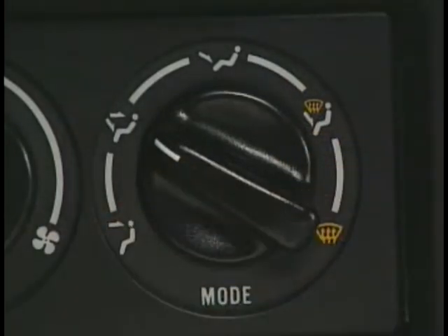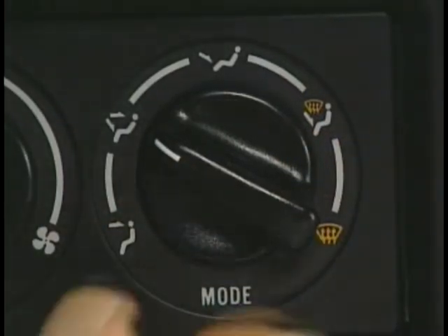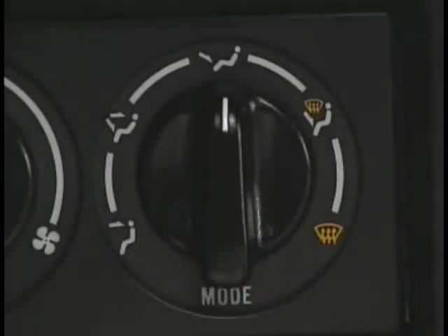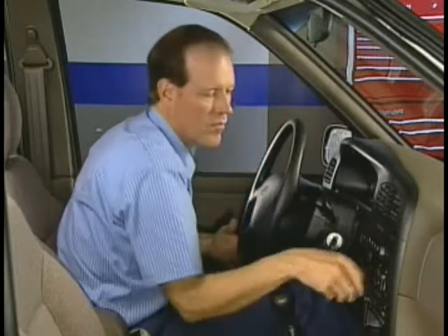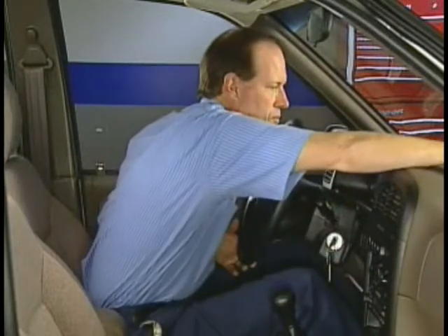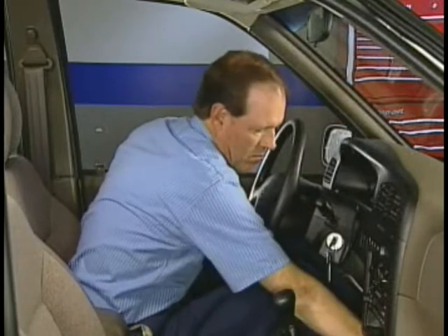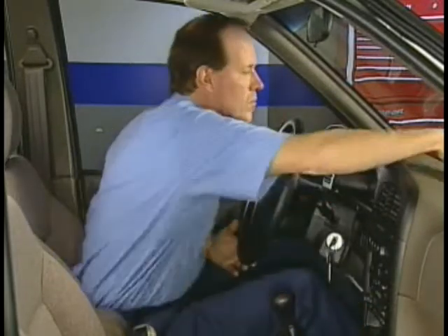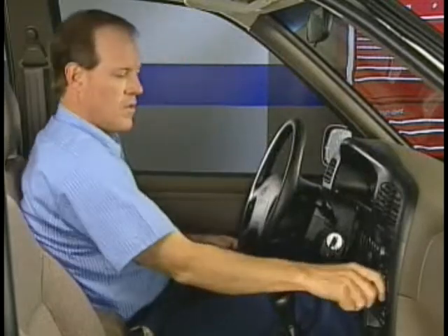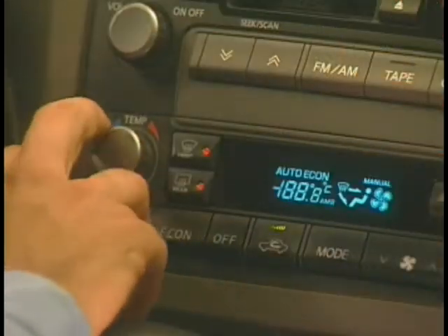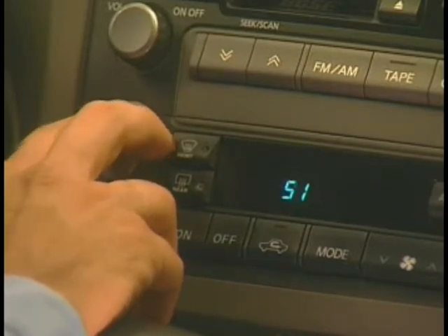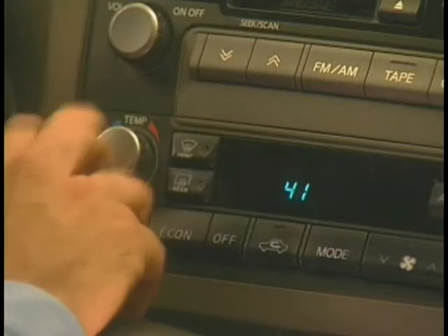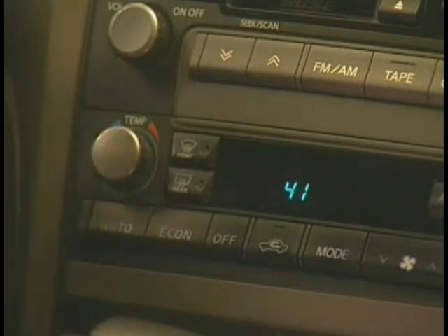Move the mode position switch through all of the positions and check for a change in the air distribution. Again, if there is no change or the airflow is diminished, check the linkages, doors, and electrical or vacuum systems to determine the cause of the problem. Air that comes out of the defroster only has a problem with the vacuum supply to the air distribution system. Automatic air conditioning systems usually have a self-diagnostic routine that will store codes in the event of an air distribution control circuit failure. The manufacturer service manual should be used to retrieve and diagnose the stored codes.